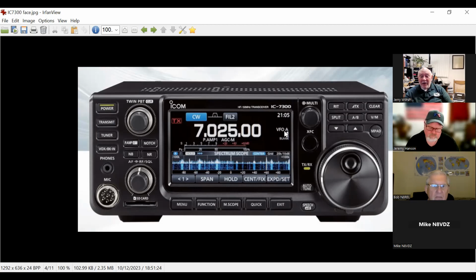One other thing that we do is operate split frequencies. I didn't explain that on the HTs. When we're working with a repeater, we're transmitting on one frequency and receiving on another frequency. When we push the push to talk button, it automatically switches the frequency, but we have to set that up.